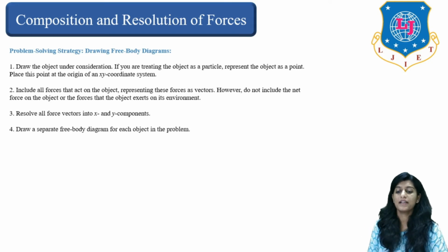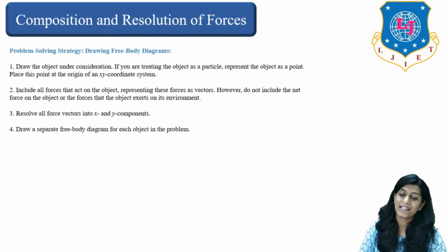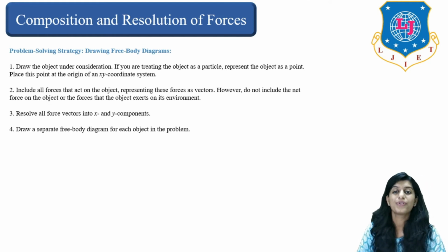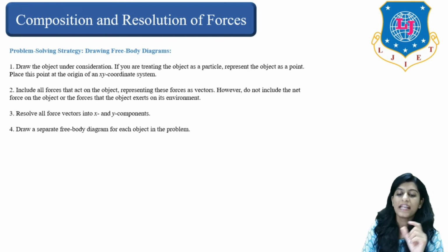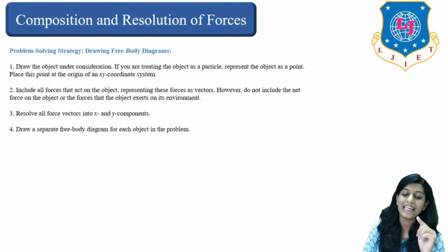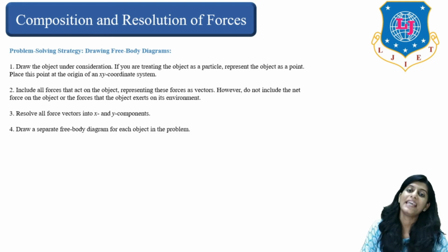Then the third point is resolve all force vectors into x and y components, right? We should resolve all forces into two components. One is the x component and another one is the y component. Now we should draw a separate free body diagram for each object in the problem. So using these four steps, we can draw a free body diagram of any component.